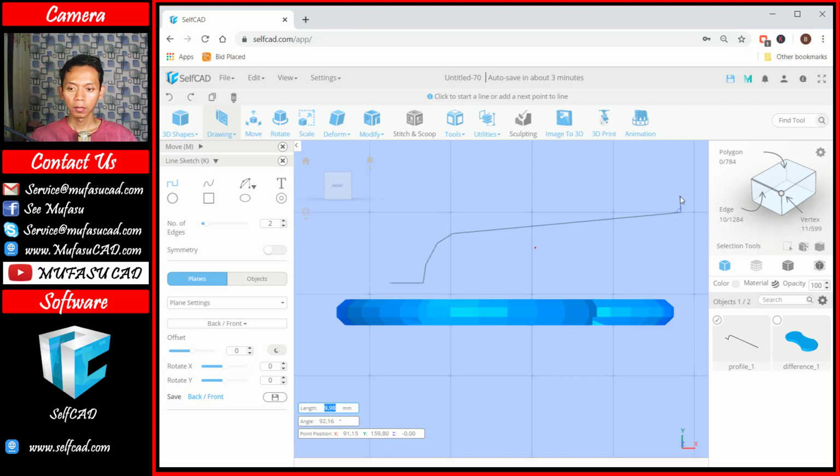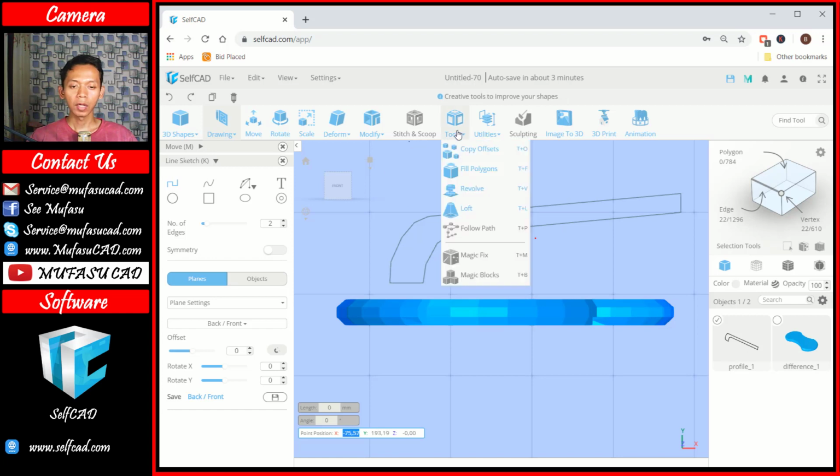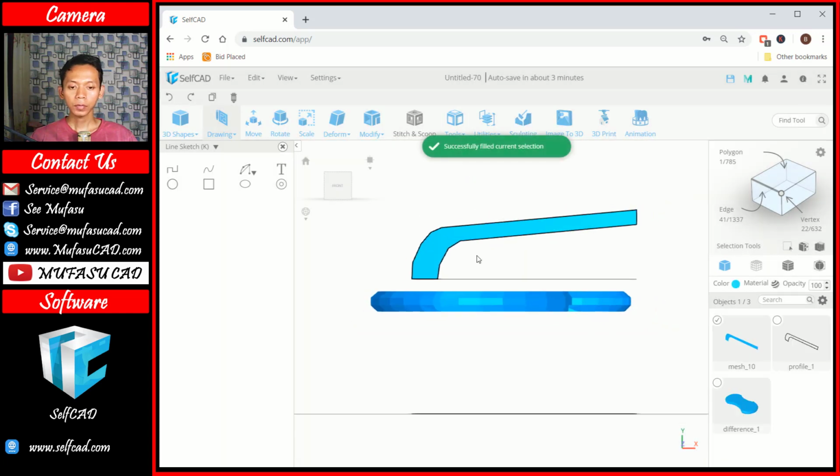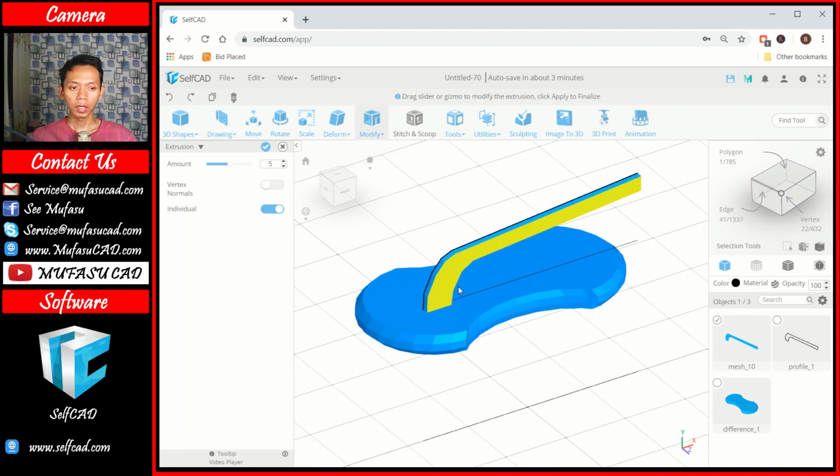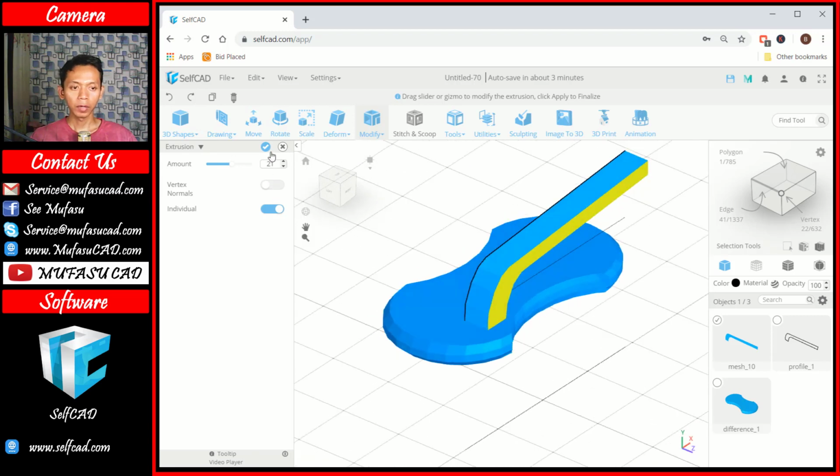Again in here. Move into this point, and then we can create cube in here. Click at this point. These are 4 handles. You can click fill polygons. Next we can use extrusion to convert into 3D models. I will change amount in here into this point 21. This is enough. Click OK.